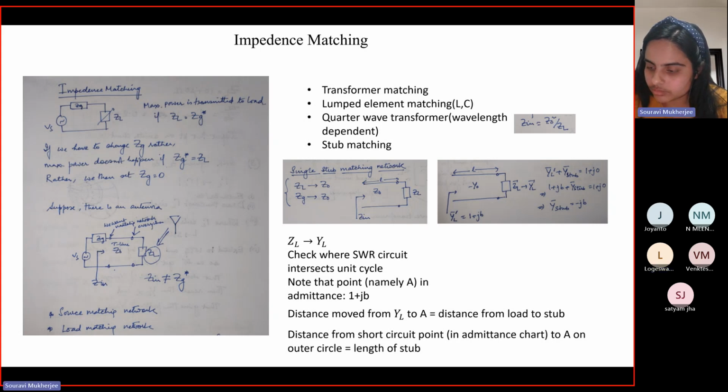No, that's why I'm asking: what is the value of Z0, sir? That Z0 is given in the question. See, if your ZL is something like 1 plus J0.2 and VSWR equal to 1, then the reflection coefficient is 0, right? That means Z0 should be equal to ZL.